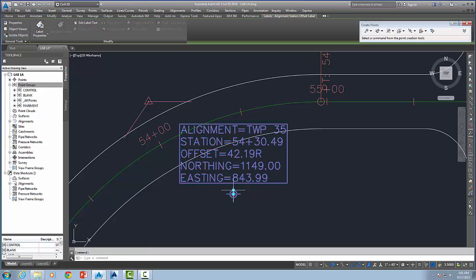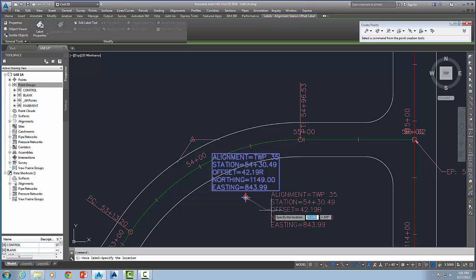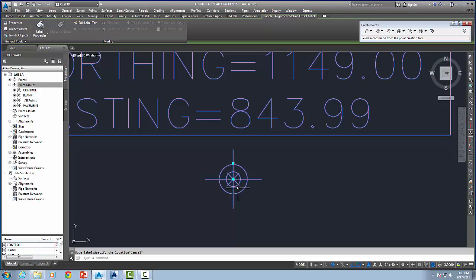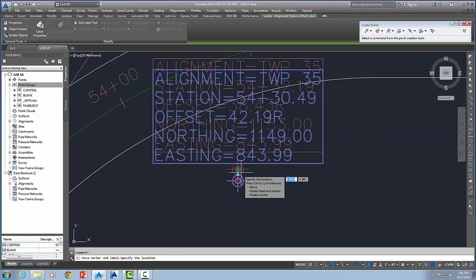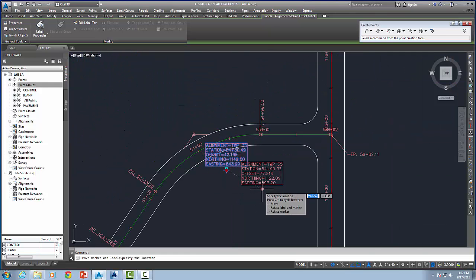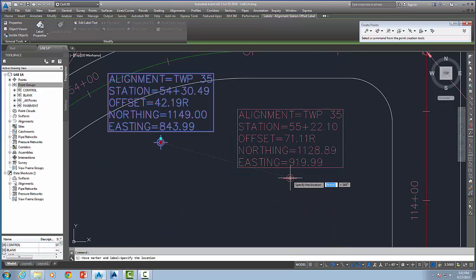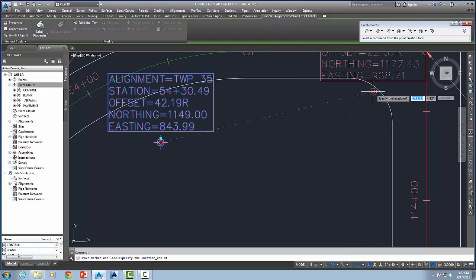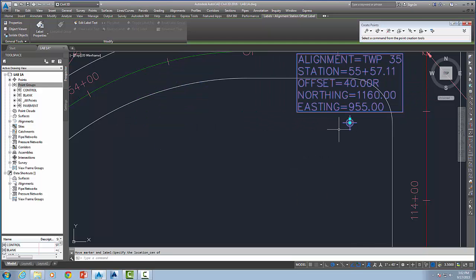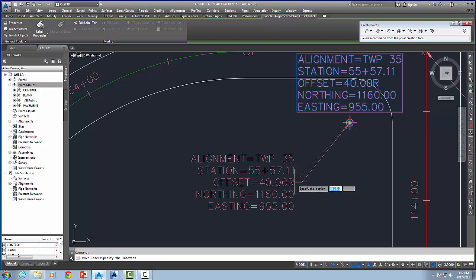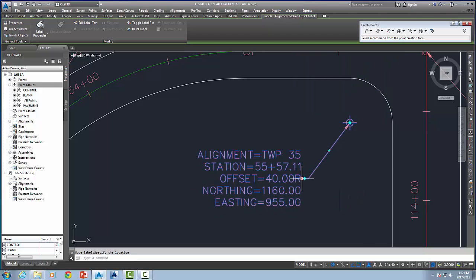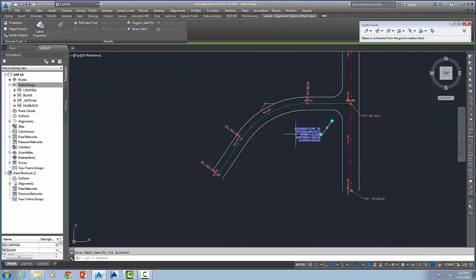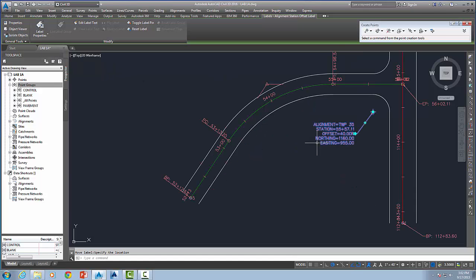You can move two things. If I move this, it's the symbol grip. If I move this, it's the point grip. So what I'm doing now, watch what's happening, is I'm floating this around. Can you see how that's actually updating? So for instance, if I wanted to go to the center point of this guy, that is showing me the information associated with the center point of this here. Or maybe we would want to do the same thing with, let's say, the center of that.